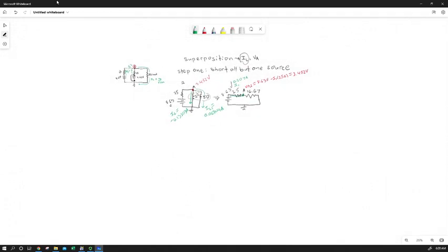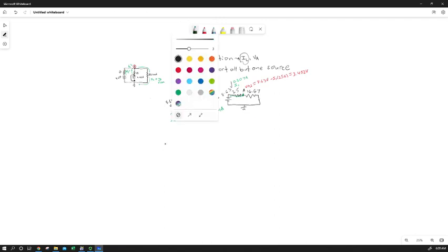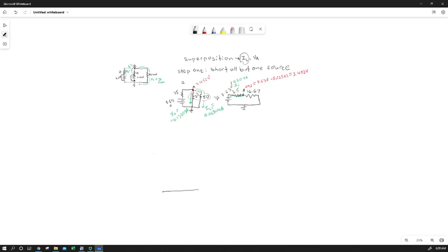So now I'm going to, not surprisingly, see what's the effect on currents and voltages due to only the source in the middle. So I'm going to short that source next. So now I've just got, here's ground, and now rather than a source and a resistor, now I have just the resistor, 25 ohms. I got that 25 ohms, and the middle source is now the only one going. This is ground. So this is step 2.